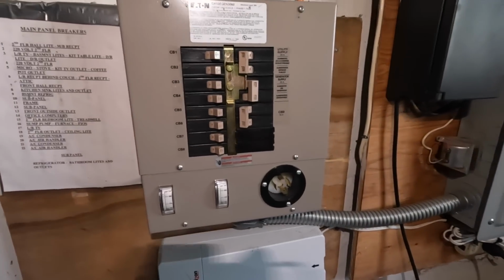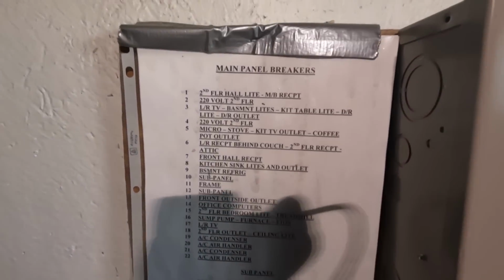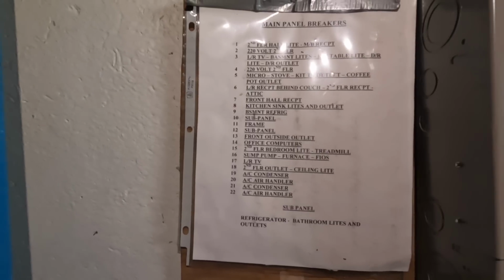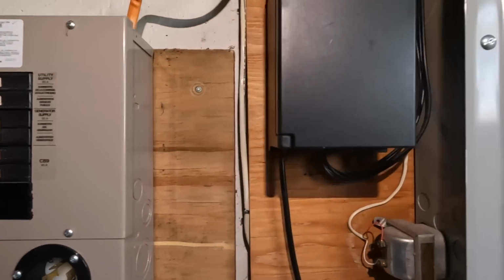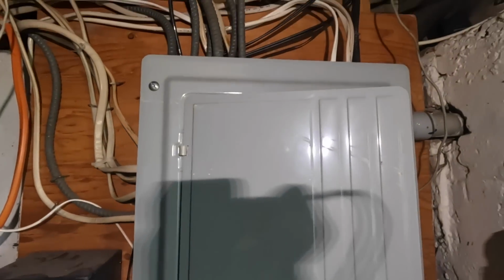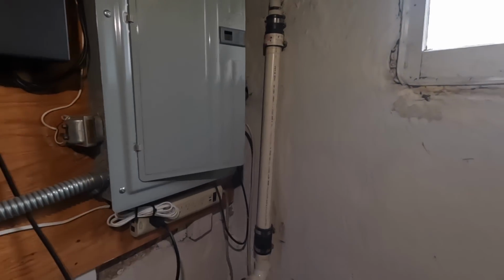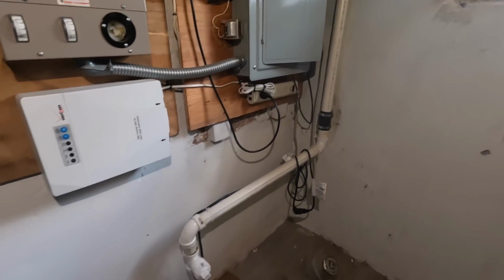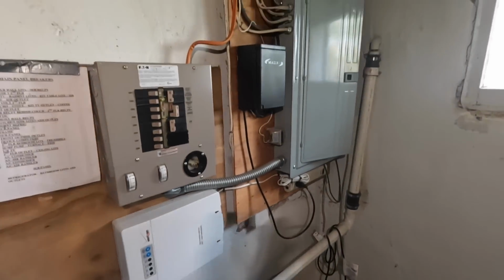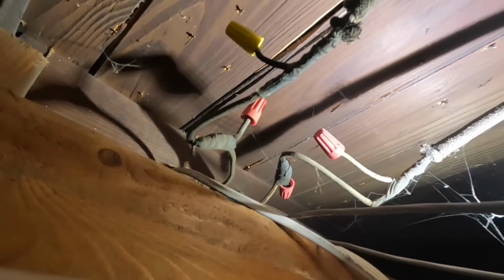Okay, so what we have here is an Eaton portable generator wiring box. As you can see, most of these breakers are labeled. I don't know how accurately. I do like the Eaton Cutler Hammer portable generator wiring box that's there. Anyhow, this is the knob and tube circuit that's going to go upstairs to the attic. We'll be rewiring that, and I believe 2 receptacles up on the second floor that are connected to that. It's a 100 amp main breaker Siemens panel, and as you can see there, that's the portable generator wiring box.